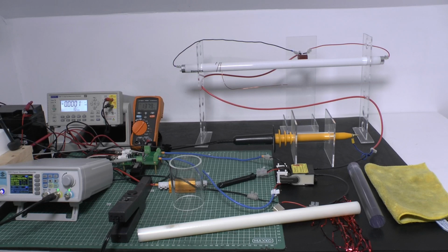So we have currently, as you can see here, 13.79 volt. I charge it via an isolated power supply, at the moment only at standby at the lowest voltage setting to keep the battery refreshed. So 13.79 volt currently, and if you take 100 ohm, it is 138 milliampere. It can maximum draw that. We're going to see here on the bigger DMM, from the current clamp, I measure the current going in. So this is some information for the power consumption.